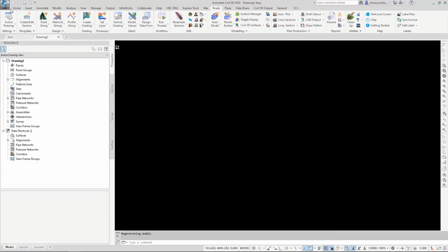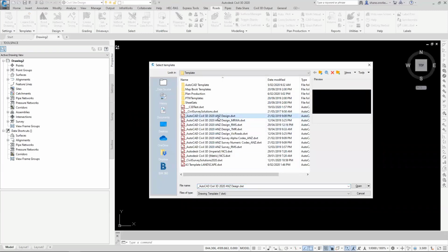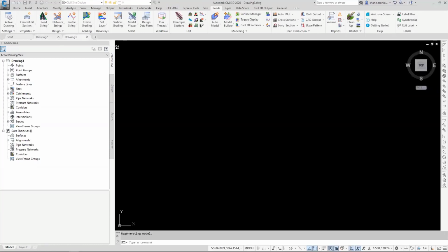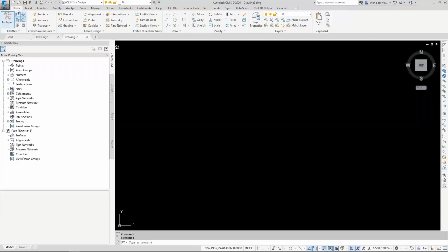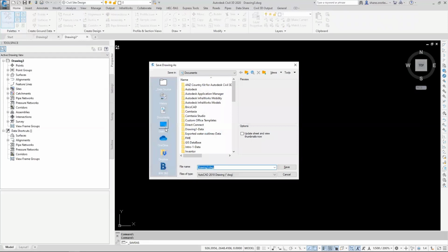And I will do that with a deliberate drawing template. So give me a moment while I flip around my options here. So I'm going to use the standard ANZ drawing template. And really what I want to show you is that as basically a receiver of information, I can stylize completely different to Todd. Okay, so Civil 3D has styles. I build on a different drawing template to Todd. Now I'm just going to save this. Currently I'm going to save it locally. So it doesn't really matter where I save it, but I'm going to put it here, call it road model.